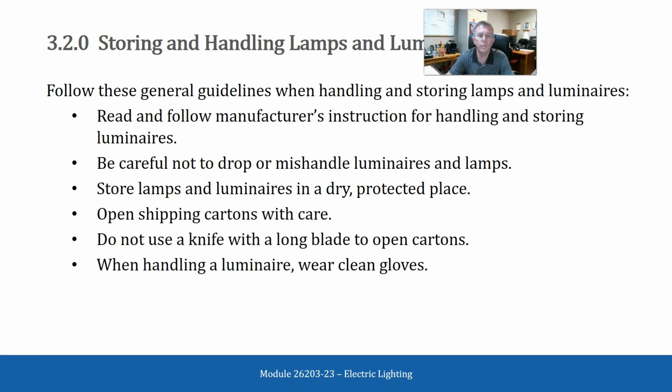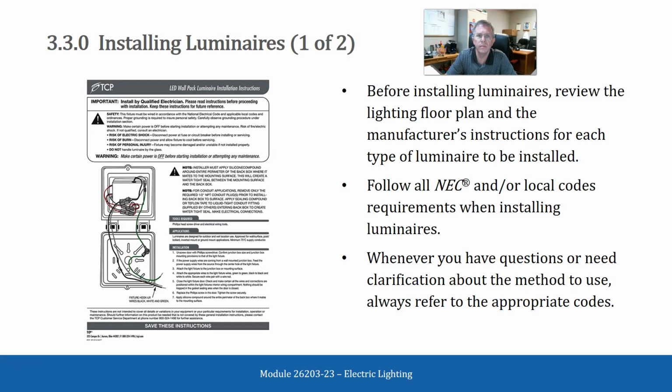Storing and handling of luminaires. Follow these general guidelines when handling and storing lamps and luminaires. Read and follow the manufacturer's instructions for handling and storage of luminaires. Be careful not to drop or mishandle luminaires and lamps. Store lamps and luminaires in a dry, protected place. Open shipping cartons with care. Do not use a knife with a long blade to open cartons. And when handling a luminaire, wear clean gloves.